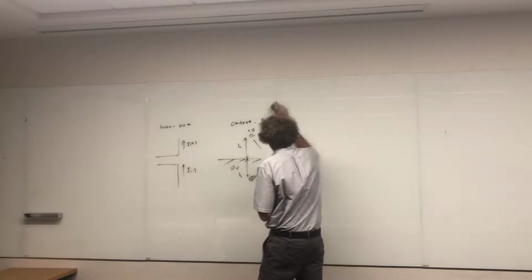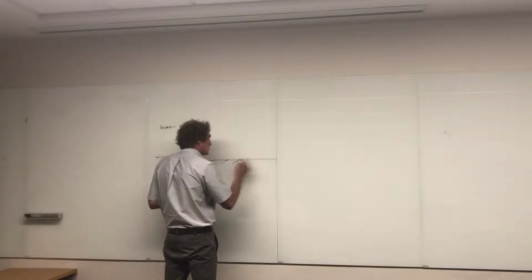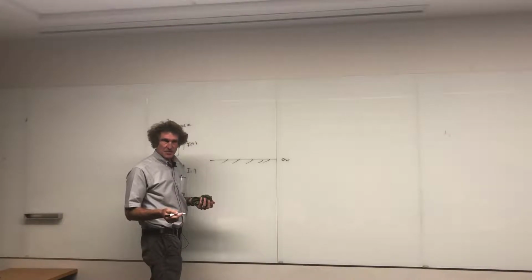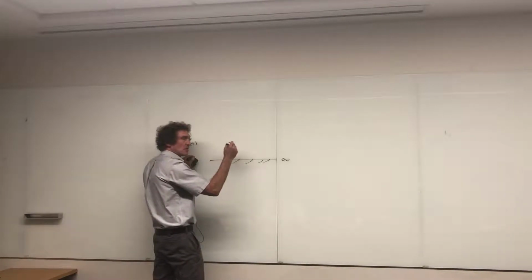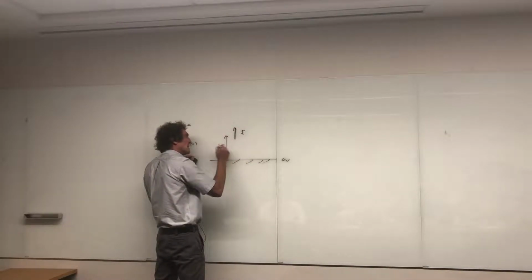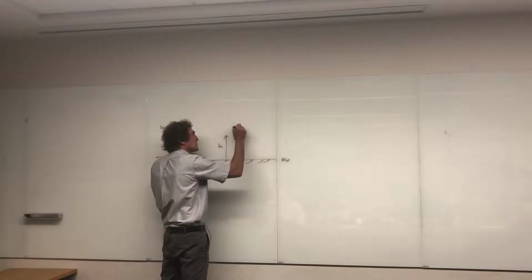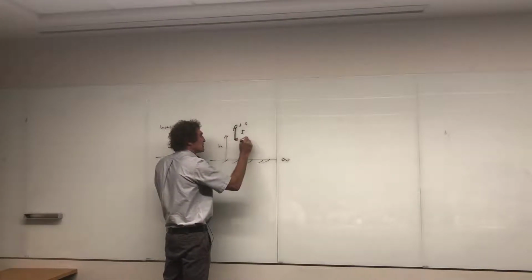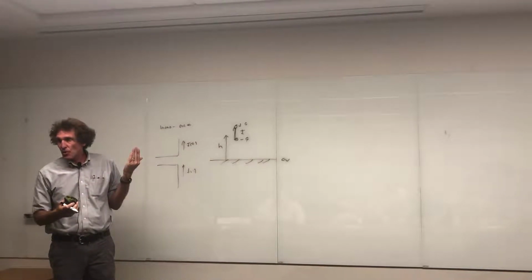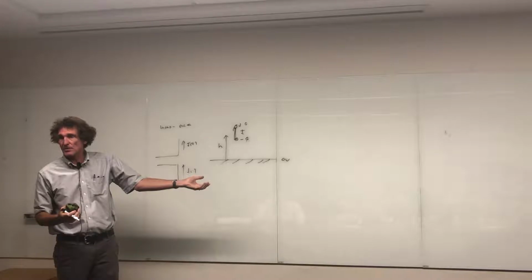When we have currents, what happens is this. Put your ground plane there. That's 0 volts, just a symbol for a ground plane. A lossy ground plane is the earth, but it's a ground plane nevertheless. If I have a current I in this direction, I want you to notice it's going to have a centroid at height h, right? Now, when I have current, think about it. Positive charge would accumulate there, and negative charge would accumulate at the base. Do you agree? Charge is moving, it accumulates positive, and there's a reservoir of negative, or it takes from the area at the bottom. Do you all understand that?